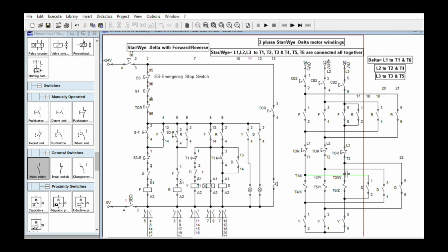And the motors can be labeled this way and refer to your motor tags. It should be this way, okay? 135 up, 246 down. That is facing the line side. This one is facing the load side. The same with overload relay. You may have RST there in European, and this one is UVW. This one is phase A, phase B, phase C of the motor.